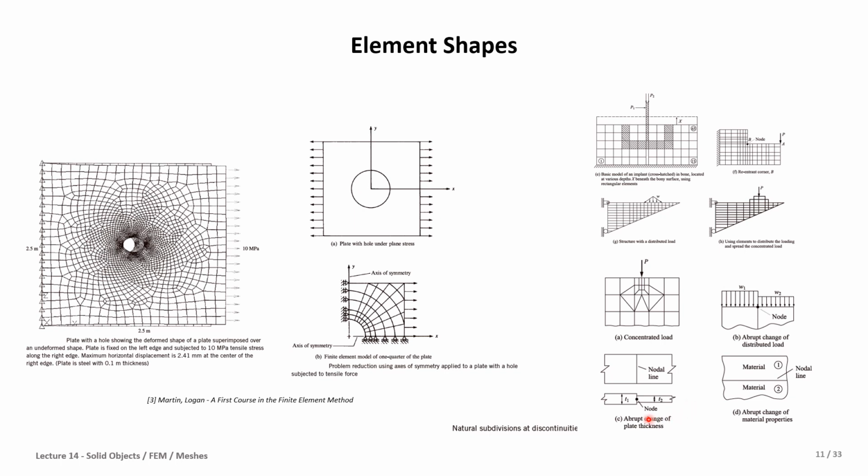If there is a difference in the section, here you can see the section is different, or we can see the thickness of this. And also about the material, when we have different materials, we need to specify the boundary and domain. So there are many issues we need to pay attention to when doing the meshing in the finite element to have a correct solution.